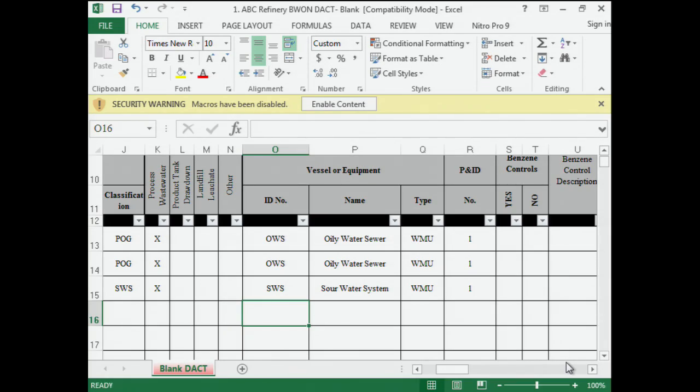If you were to go through this exercise, flip through your P&IDs and practice picking out your points of generation, your double counts, things like that, and enter them into the spreadsheet. You don't have to do all of them. We don't expect you to go through the whole book, but this is just giving you an exercise of documenting your waste streams.